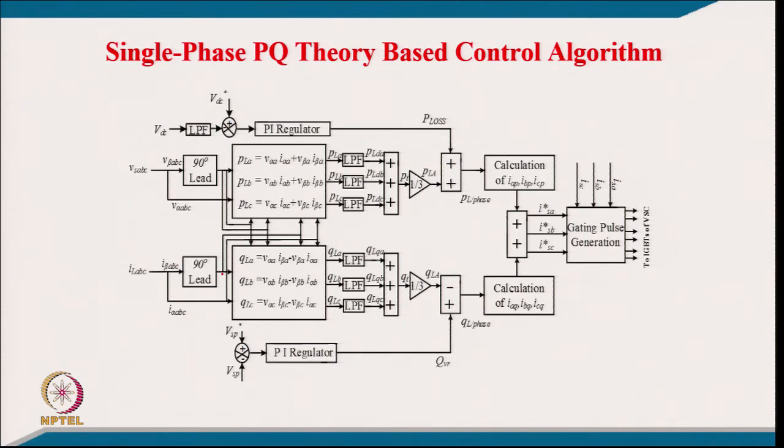All these we use in calculating the instantaneous active power for all three phases, each considered equivalent to a two phase alpha beta system, similarly for B phase, similarly for C phase. Similarly we take it for the reactive power for all 3 phases from alpha beta by cross coupling, using this expression. So, this gives the reactive power for all 3 phases A, B, C, and of course, it consists of ripple.